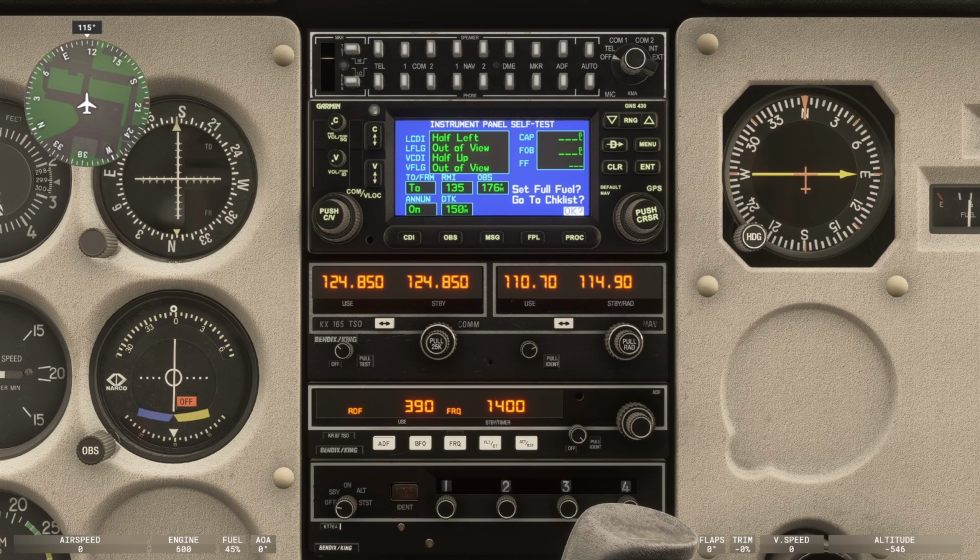So it's measured in gallons per hour, GPH, or liters per hour, LPH, and it differs per aircraft, and some aircraft might have a sensor which will show you the actual value. If you don't have it, then you will need to look up the fuel flow described in the manual of the aircraft. For example, for a Cessna 185, the fuel flow is around 14 GPH during cruise, and it can go up to 18 GPH depending on the power settings and conditions, right? There are a lot of things which you need to keep in mind. It's also important to, of course, monitor the fuel flow.